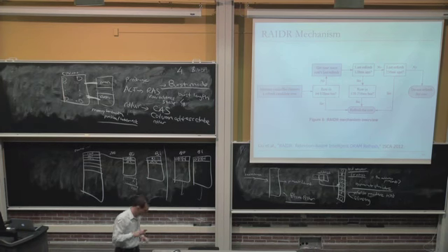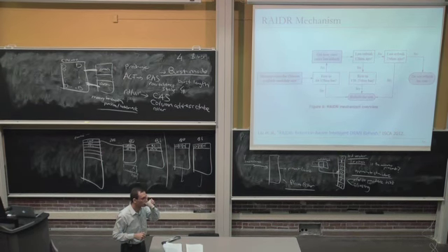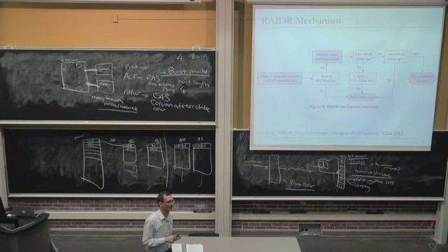Okay, yes? Since it's a manufacturing thing due to which you have different refresh times, how do you ensure that, suppose there's a chip in which all of the DRAM cells have to be refreshed within the minimum time? At that time, your 64 to 128 milliseconds bin should contain all the rows.